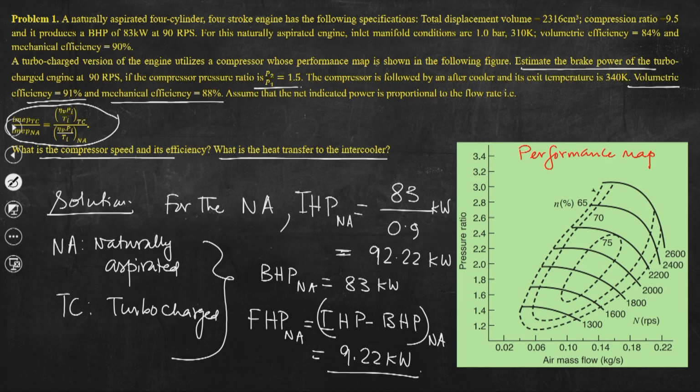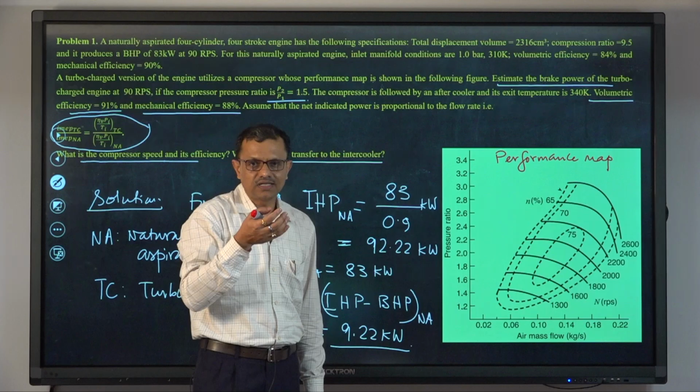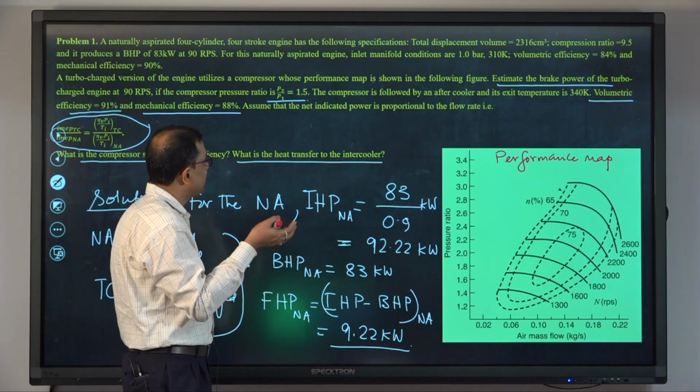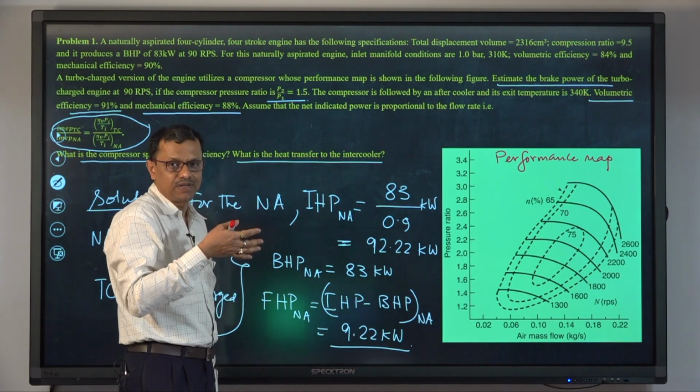See, for the turbocharged engine, the manifold condition, that is air temperature and air pressure at the inlet manifold, will be dictated by the exit condition of the compressor.